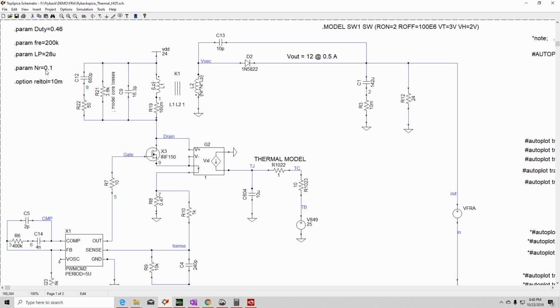How does it do that? If you notice here, it says V times I. So what it does is, right here, we break the leg of the source and we route it into the current measurement. This node measures the current going through the transistor, and that value is placed there.